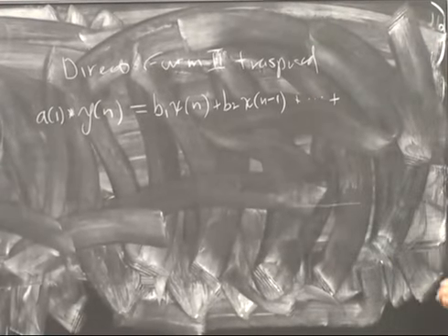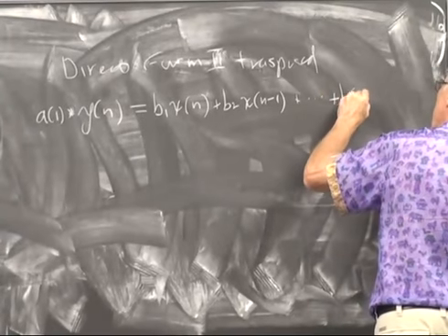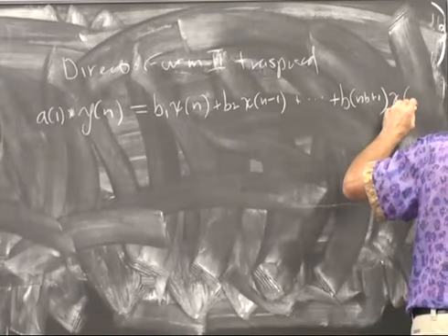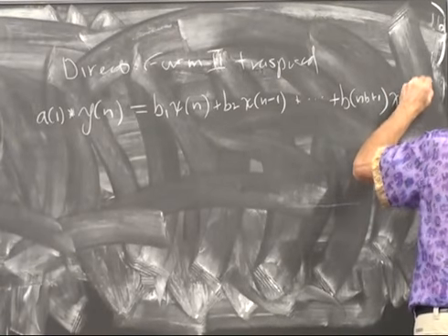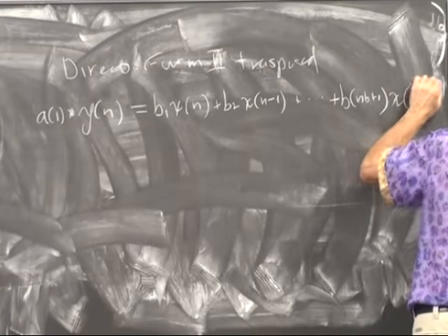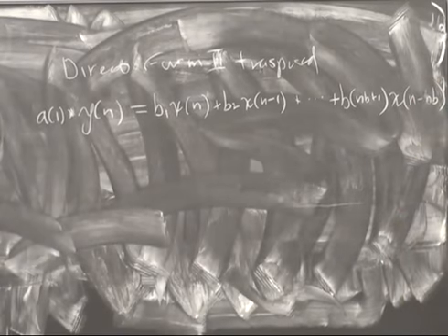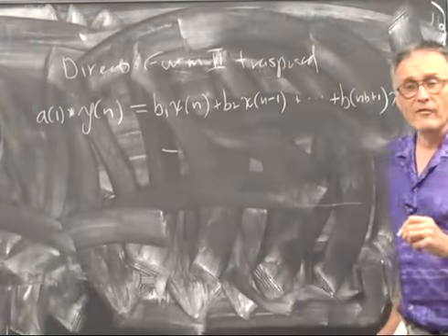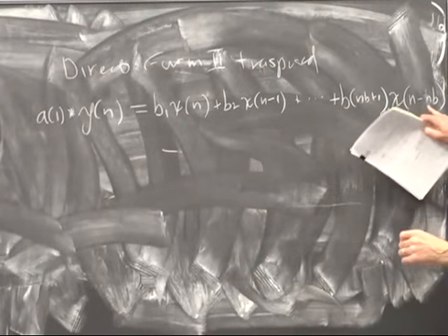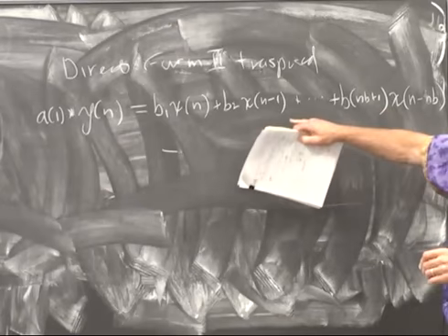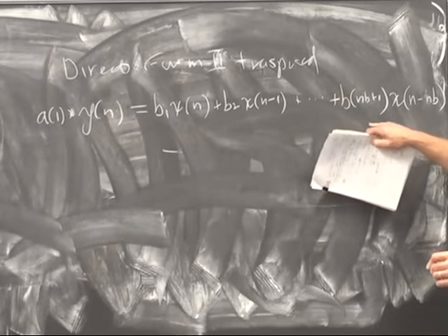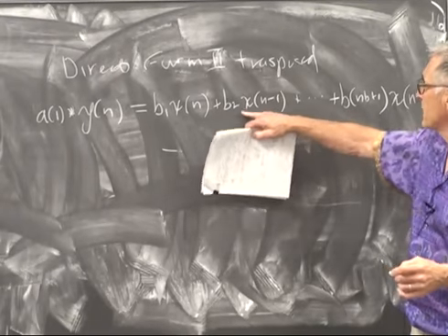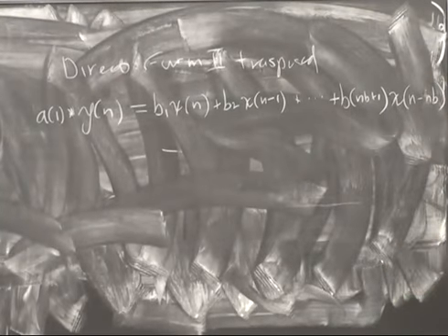And we're going to do some number of samples up to b of nb plus 1 times x of time n minus nb, and that's all the information we have about the input. We can use as many samples as we want, but in the end we have to have a finite sum, and if we want the system to be linear, we have to use a linear constant coefficient filter. We have to use constant coefficients multiplied by each input value.